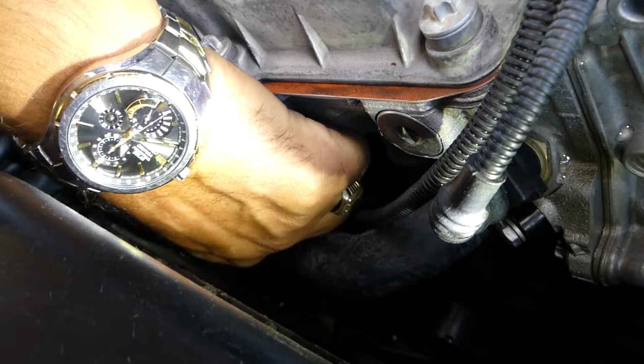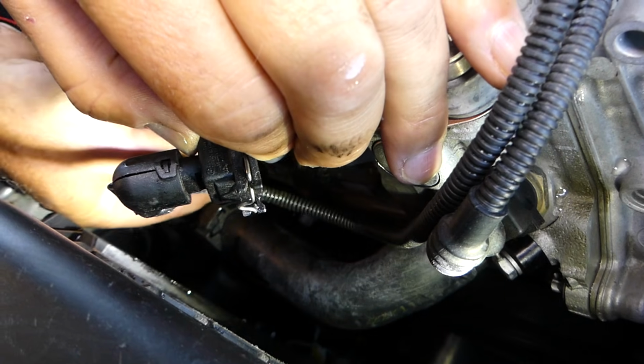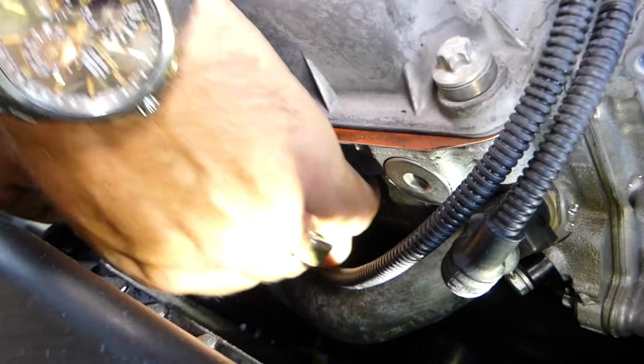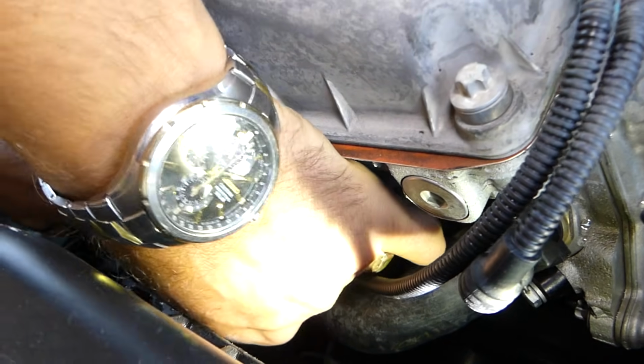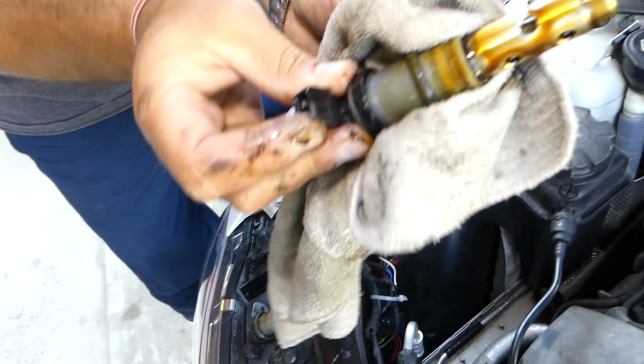And this guy is pretty stuck as well. So we have to move it a little bit left and right, and you eventually come out. You leak some oil, so you have to wash your engine later after you install them, so you don't get any water inside. Okay, and this is the second valve out of the way now.